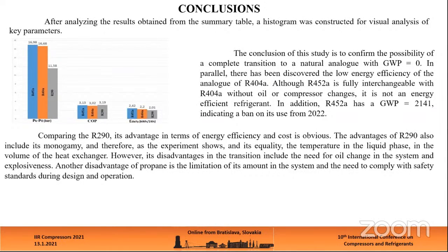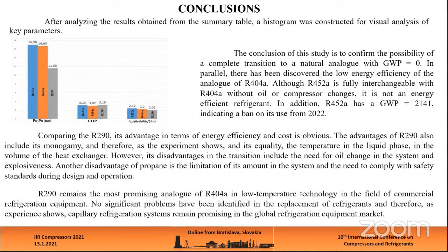Another disadvantage of propane is the limitation of its amount in the system and the need to comply with safety standards during design and operation. R290 remains the most promising analog of R404A in low-temperature technology in the field of commercial refrigeration equipment. No significant problems have been identified in the replacement of refrigerants, and therefore, as experience shows, capillary refrigeration systems remain promising in the global refrigeration equipment market.